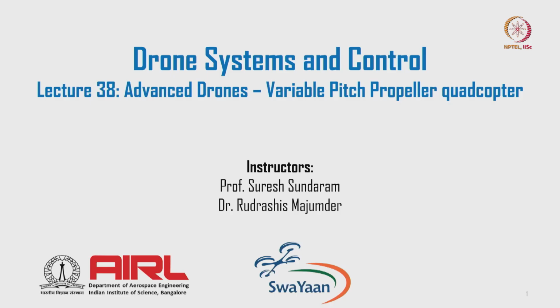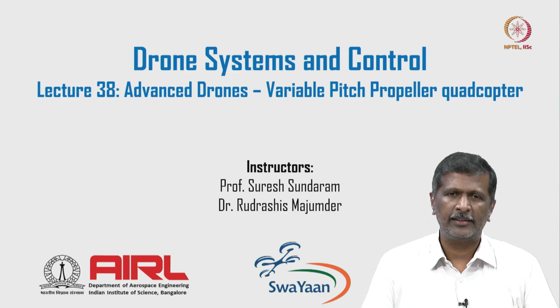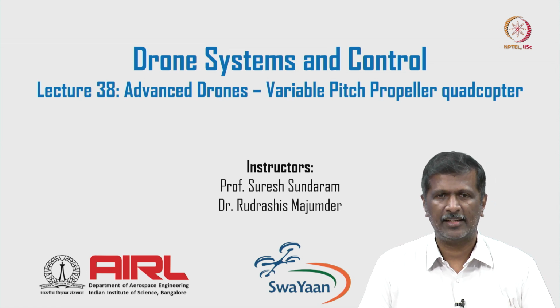It's lecture 38. We are going to talk about an advanced drone called the variable pitch quadcopter. This particular quadcopter is designed to operate even under failure, even one complete actuator failure. How can you take this quadcopter and complete the mission? What we basically mean is, can I achieve full attitude performance even if I lose one motor and propeller, without yawing, and maneuver and land safely?